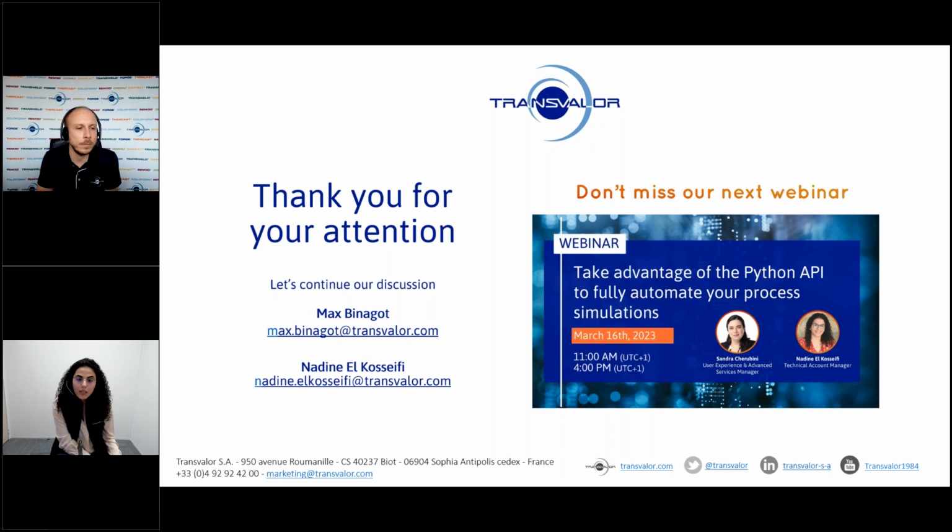Yes. Thank you. So, last question, because we already get to the end of this webinar. Concerning post-processing with the Python API, is there a way to combine nodal and 3D element results, to see at the same time results that are nodal and 3D element? Yes, there are no restrictions. You can display, for example, the contact on the right and another field which is calculated on elements on the other side. There is no restriction like that. No restriction for the display, no restriction for the export, and so on.